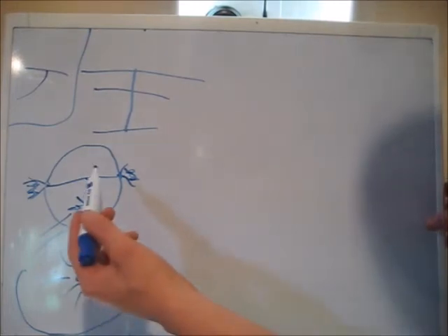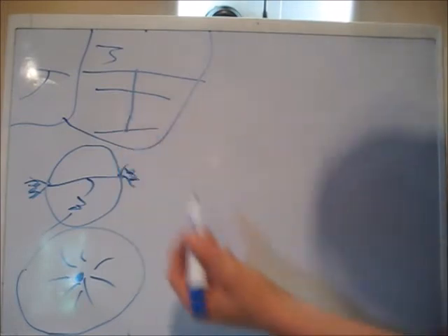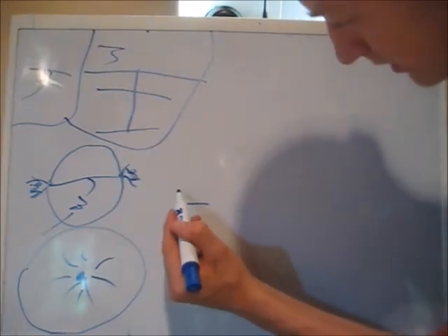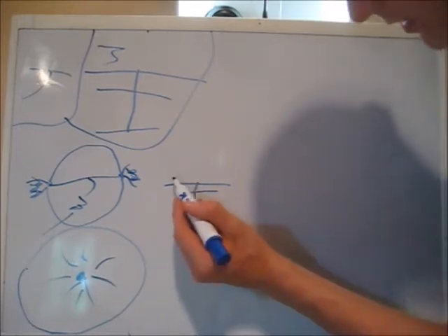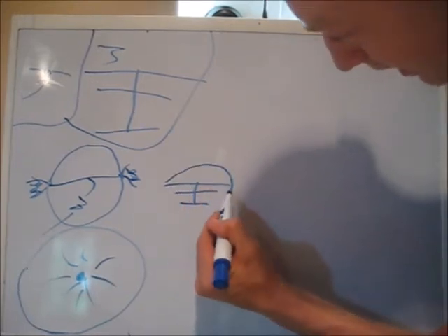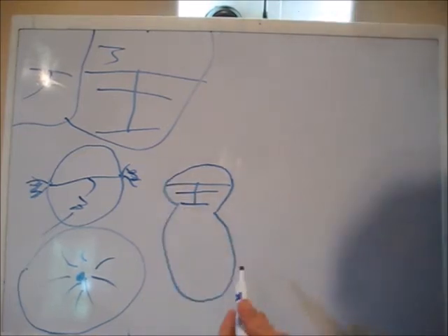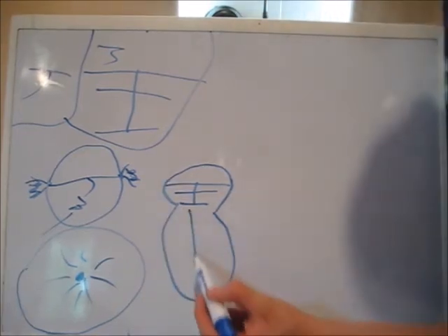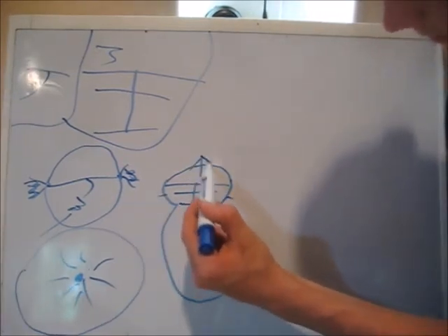So a beam antenna, which is antenna number 3 here, radiates more like this. Let me draw a smaller version here. It radiates more like this. It has a very small radiation in the back, very small off the side. But when you get in the front, it has a much larger radiation. So most of the power is going forward with a little bit to the sides and a medium amount to the back.